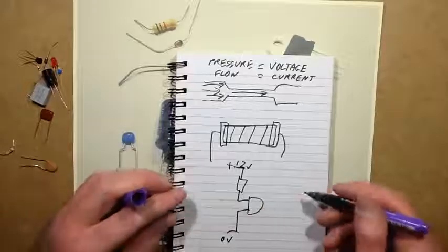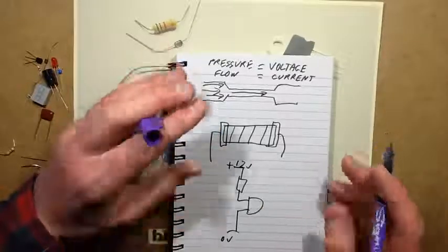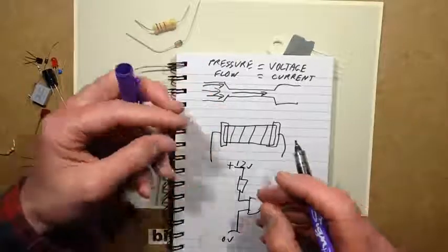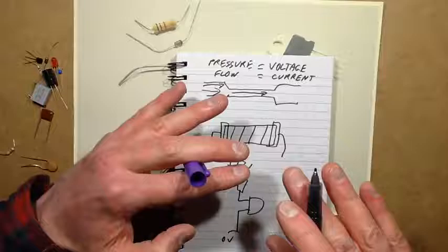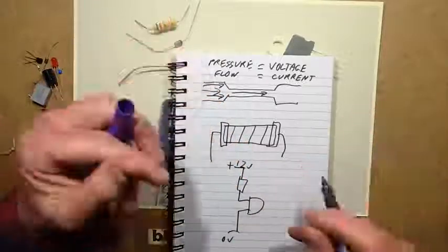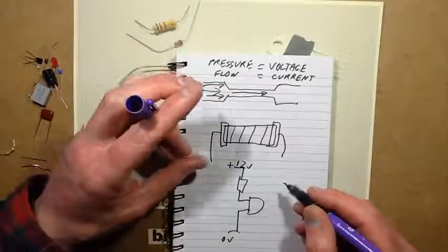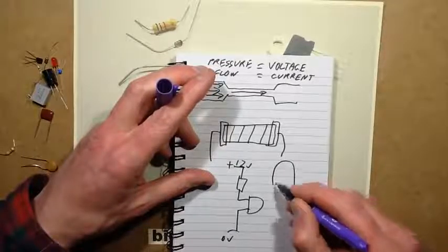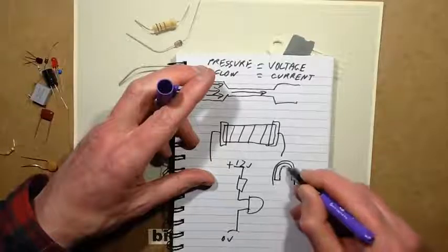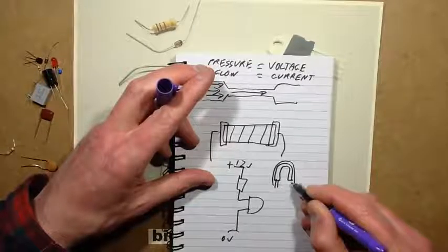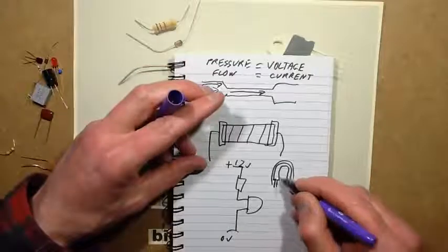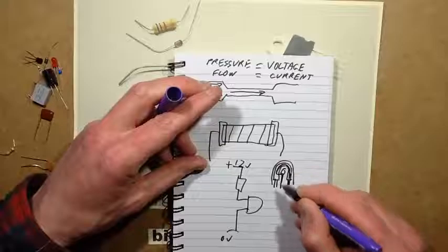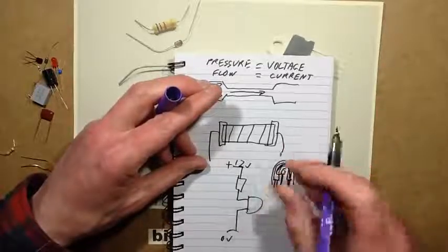They're also used for things like time delays. You might have a resistor charging up a capacitor, it trickles the current into it until the voltage reaches a certain level, and then that could be used as a timing function. And you also get variable resistors where effectively it's a carbon track connected at both ends. You only really need to use it connected at one end, and with a wiper that actually wipes round that track, so that depending on its position that will vary the resistance.